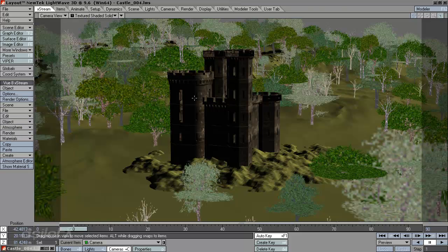I also want to note that anytime you have an ecosystem populated, it will increase the size of the file. If you haven't painted any part of the ecosystem in standalone version, one thing you can do is clear the ecosystem population from the material, save it, and it'll be a much smaller file size. So then when you reopen the scene, you can just repopulate it. With dynamic population, it just ends up automatically clearing everything out and reloading only when you render.